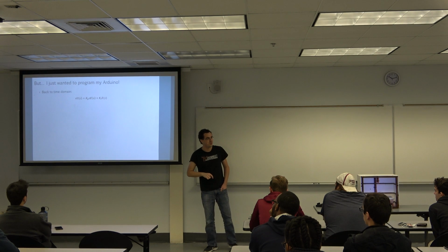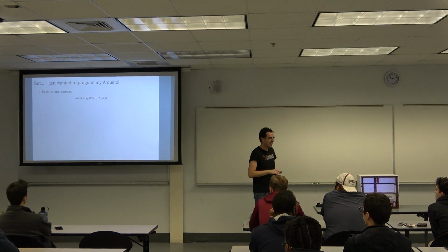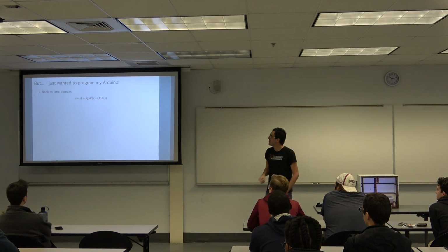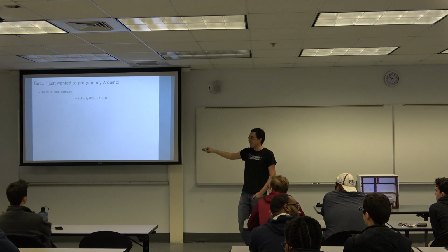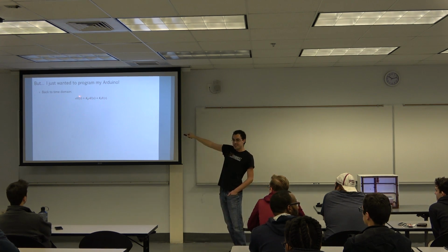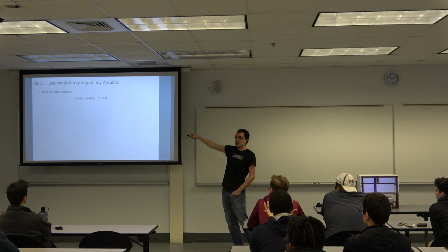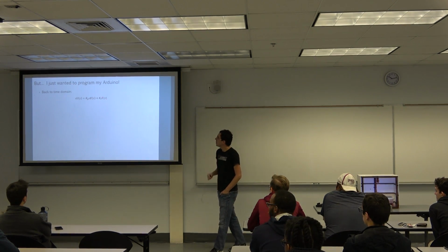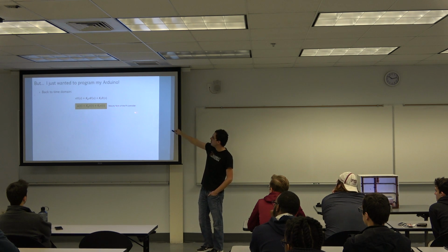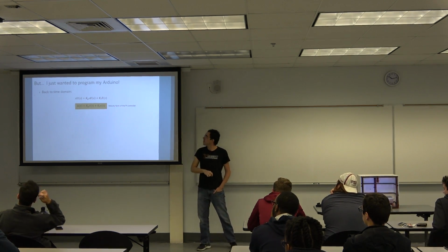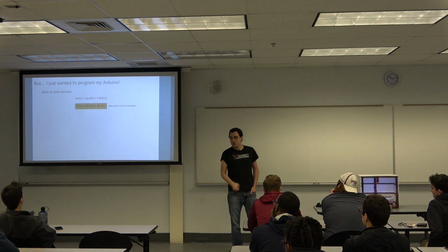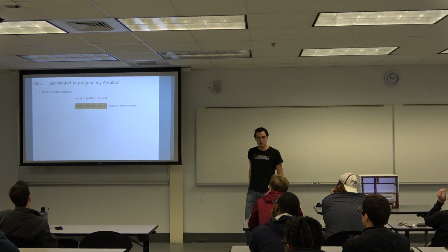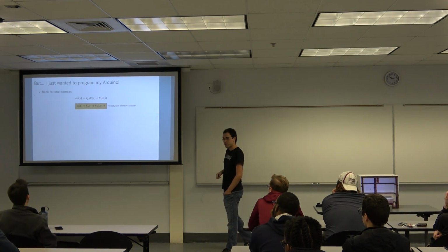And if we do an inverse Laplace transform, assuming zero initial conditions, how would it look? Anyone have a guess? U dot. That's U dot, exactly. KP times E dot, and that's just E, right? E of t. So then we get U dot equals KP E dot plus KI E. And this is what we call the velocity form of the PI controller.